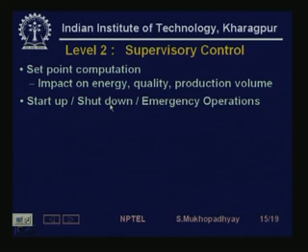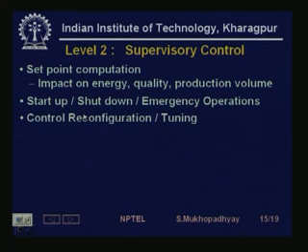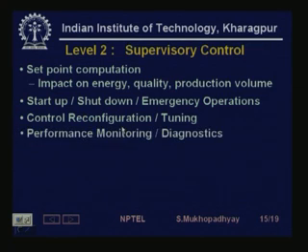So it does startup, shutdown and various kinds of emergency operations. It does control reconfiguration and tuning. You may have to change the controller from time to time. It does performance monitoring. Is the loop properly tuned? Is there a sensor malfunction? It continuously checks. It provides an operator interface.